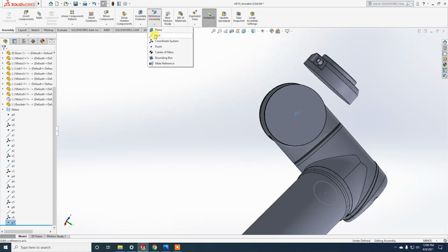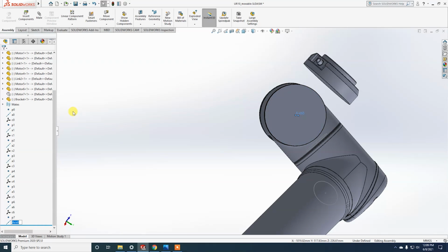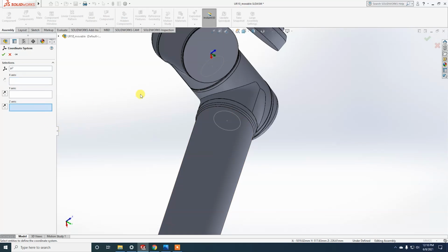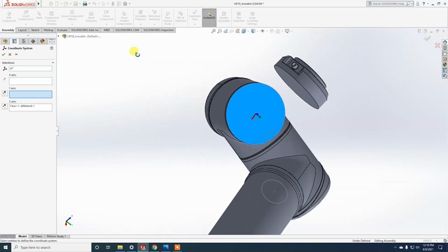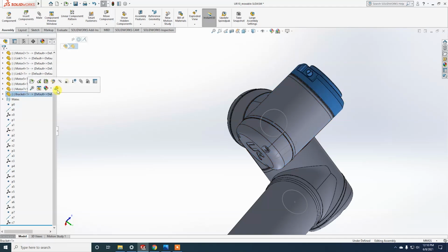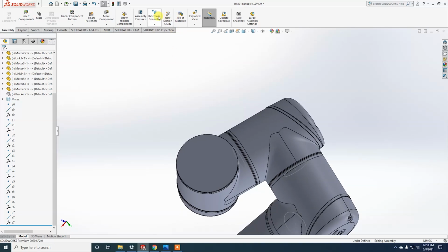While this point is selected, hit axis. Okay, A7, and now again select point 7 and place coordinates there, and the Z-axis is not in an appropriate direction, so let's hit it this way. So now it is good. Let's call this C7 again, and now we unhide it, and let's drop this bracket, and now we have to repeat the procedure here.